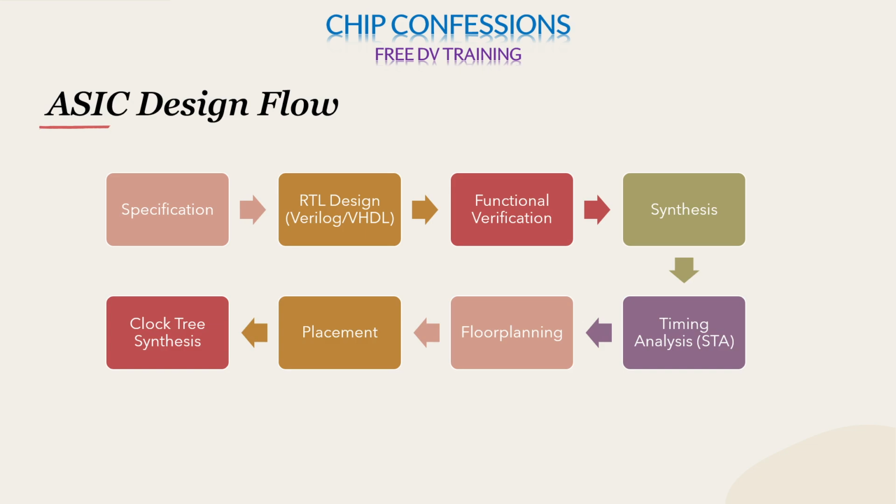After your placement, it will check how the clock can reach everywhere, and at what time. Here also, we will be ensuring the clock signal is reaching all the flip-flops at the right time. Delay will be there everywhere. We can't say zero delay, because zero delay is such an ideal condition, it can never exist. So what we can see is whether the clock is reaching at the right time or not. That we will see in clock tree synthesis. Then the next step is nothing but your routing. What this routing will do, it will connect.